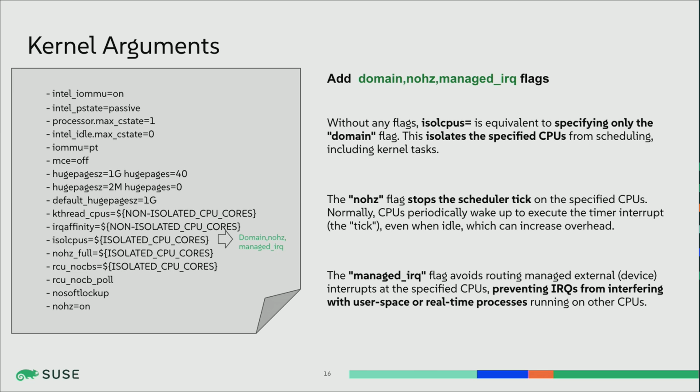This is really important, and sometimes really complex to do, because when you are defining your application, you could imagine that it's going to be pinned to a specific CPU. The problem is that sometimes it has different devices and IOs, and you cannot control where the IRQ is going to happen. So with this parameter, you are able to at least limit the number of CPUs that manage the IRQs, which is something that increases the latency in applications a lot.